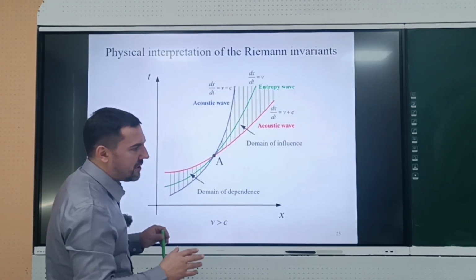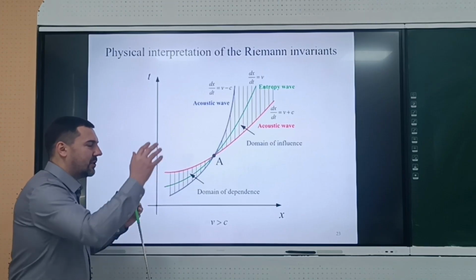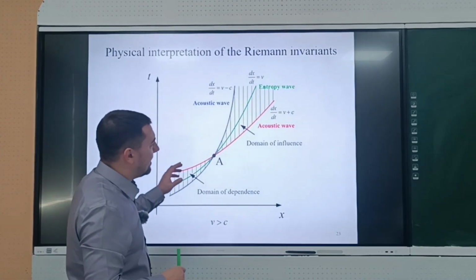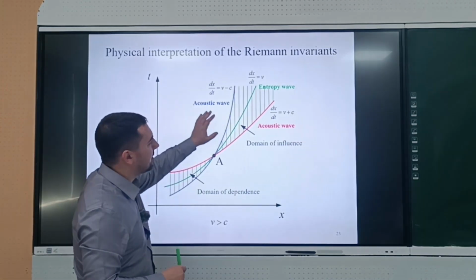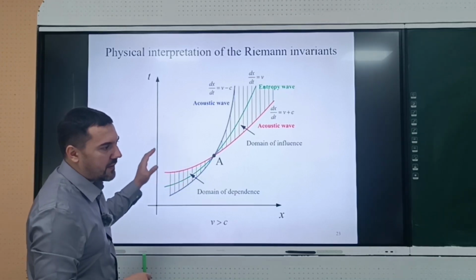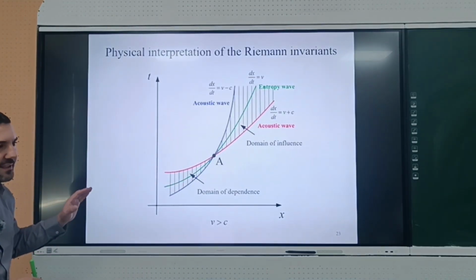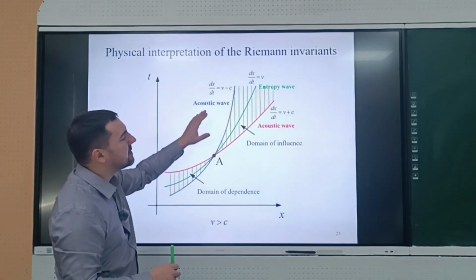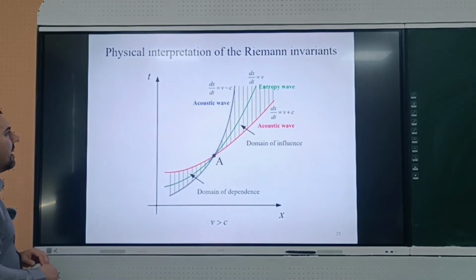So if you have some good numerical method, you can expect that everything is already inside and it will get the correct solution. But actually, usually not, because it's your responsibility, at least, to impose correct boundary conditions, so realize the influence of your boundary conditions on your result. For example, if you compute subsonic flows.